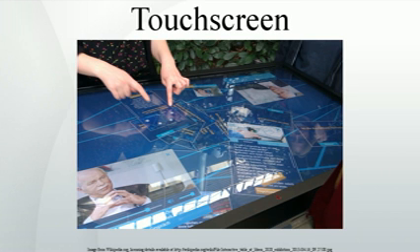The sensor's controller can determine the location of the touch indirectly from the change in the capacitance as measured from the four corners of the panel. As it has no moving parts, it is moderately durable but has limited resolution, is prone to false signals from parasitic capacitive coupling, and needs calibration during manufacture. It is therefore most often used in simple applications such as industrial controls and kiosks.